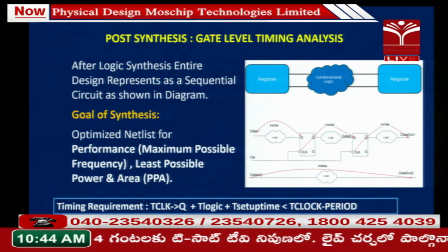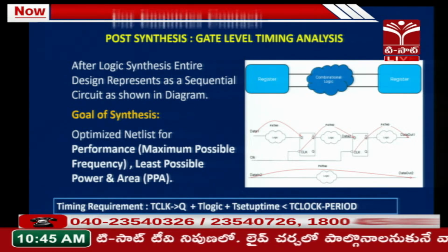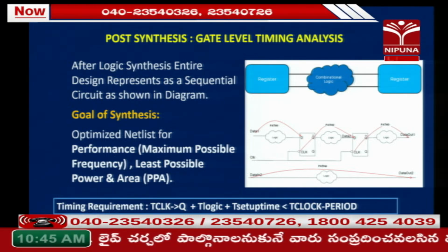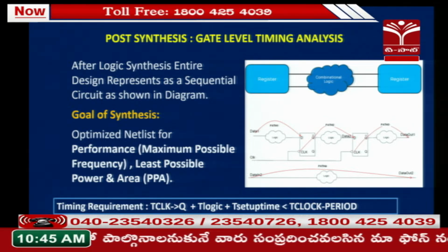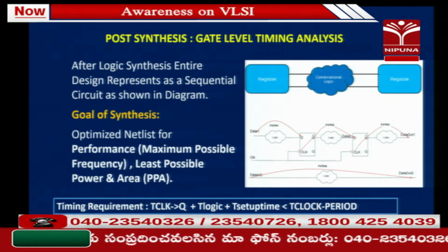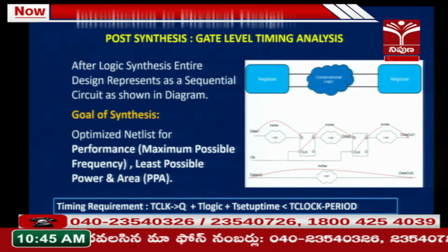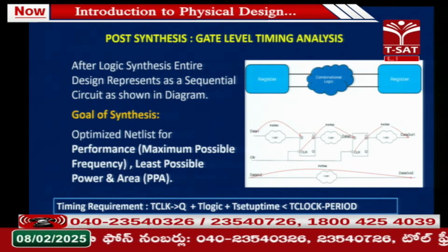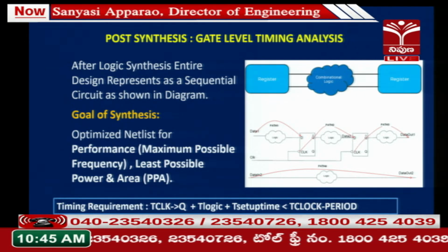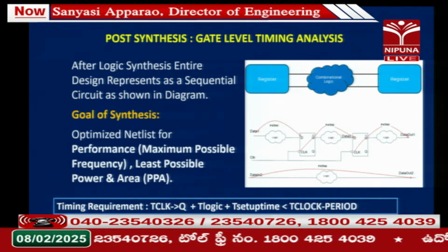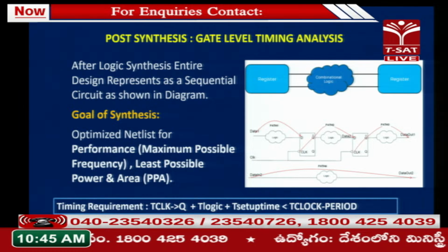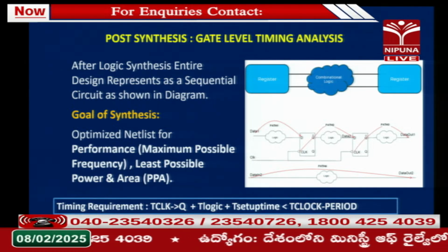If you look at the bottom diagram, the first one is the data path, that is your IO pad, input to your chip. That is going to a logic, and that logic is going to the D pin of your flop. Generally, you have different sequential cells, right? JK flip flop, D flip flop, like that. In general, people use D flip flops in ASIC design. So, that is the D pin of the flop.